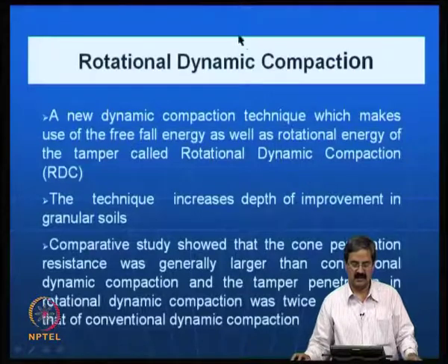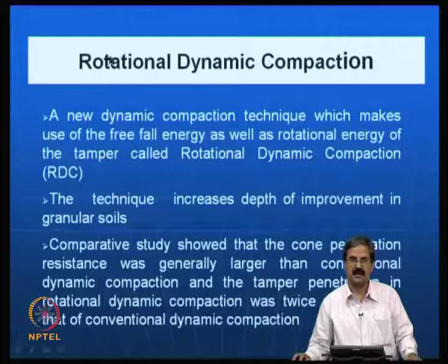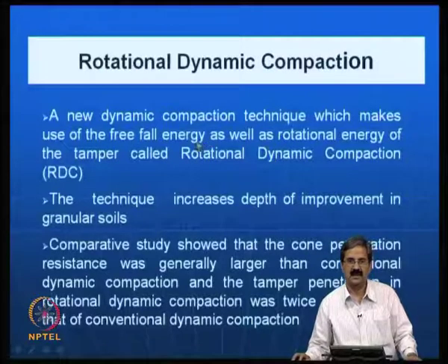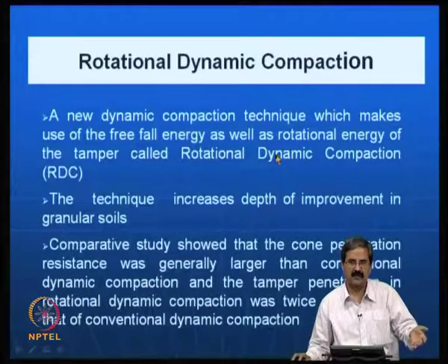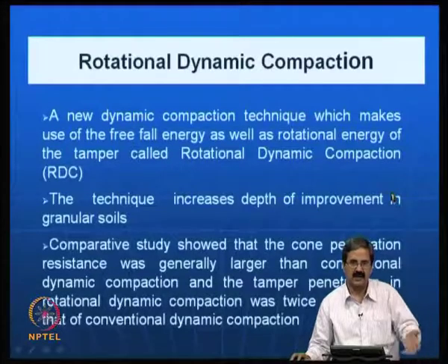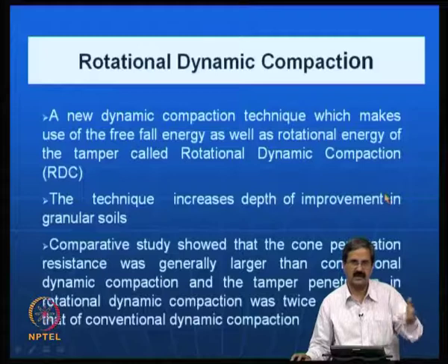Then what is known as rotational dynamic compaction is also possible, because people have done some studies on a new method in which free fall energy is used. Like we know, you drop a weight and there is free fall energy, then you rotate it also, so in that same place there is a rotational energy as well.